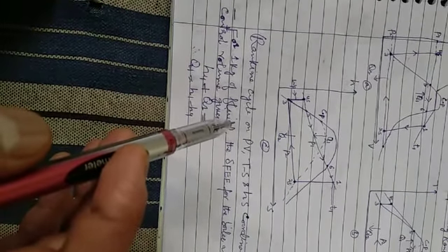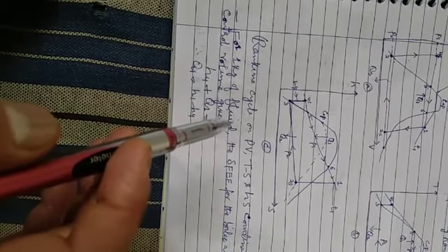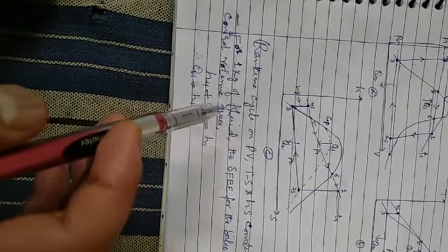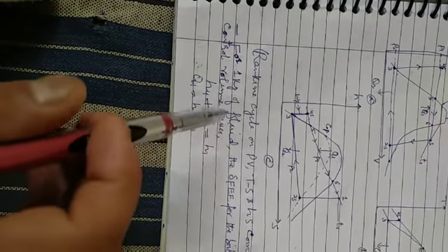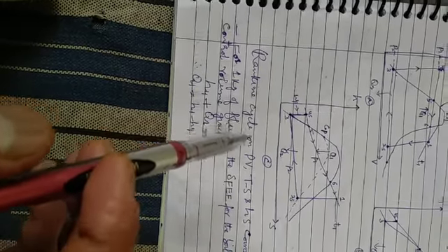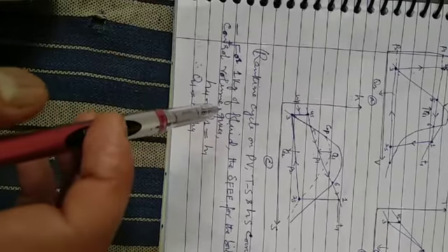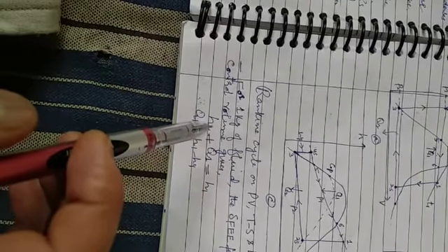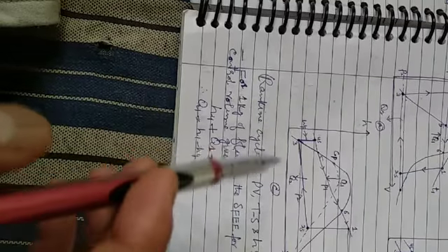The steady flow energy equation is also available in my notes; you have to read it first. You also have to consider that the change in kinetic energy and potential energy of the steam and water in the cycle remains constant, and they are neglected here. That is why we are using only enthalpy, heat transfer, and work done in all the processes.